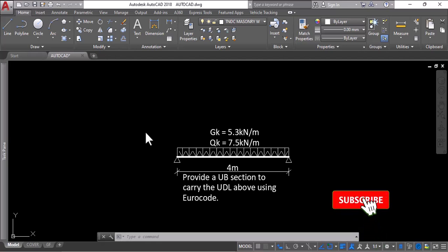So today I'm going to show you how to design a simply supported beam. Looking at the AutoCAD file, you will notice that our question says provide a UB section to carry the UDL above using Eurocode. The question says that the GK permanent load is 5.3 kN per meter and our variable load, that's QK, is 7.5 kN per meter.